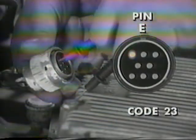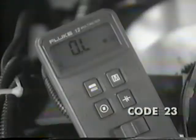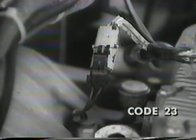Now, there's a short to ground test too. Clamp one probe to chassis ground. Use the other to probe terminal E. It should be open. This one checks OK. If either of these checks failed, work your way down to the sensor.